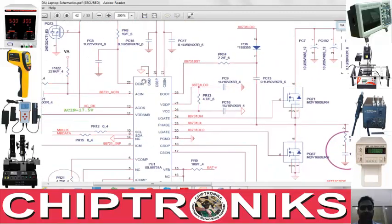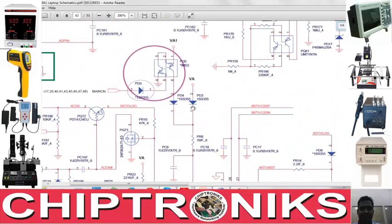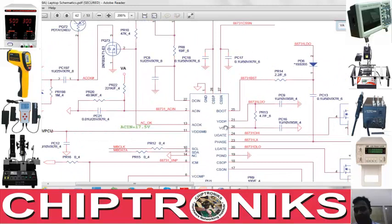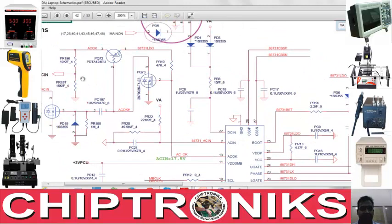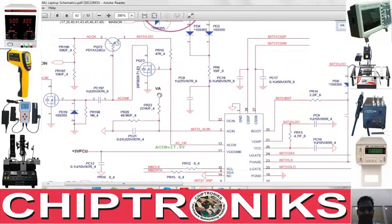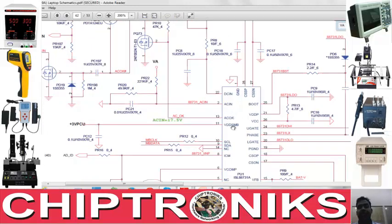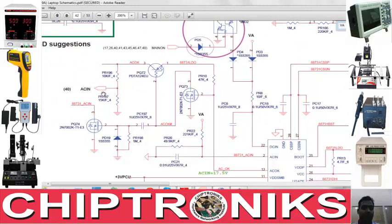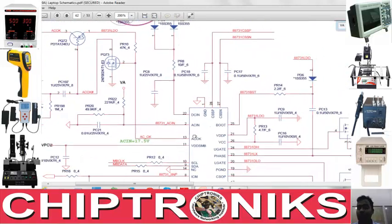This charger IC, the VA is going to the DC in, and it will generate an LDO voltage, so it will come across this VDDP, and the same VA through a resistance divider is going to AC in. So this charger IC will give a digital output of AC_OK, and it will go to create an AC in signal, and that will go to the IO controller, right? That will go to the IO controller.